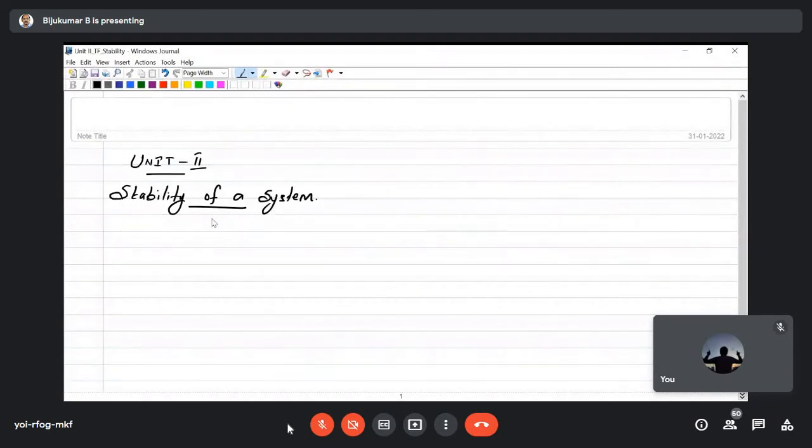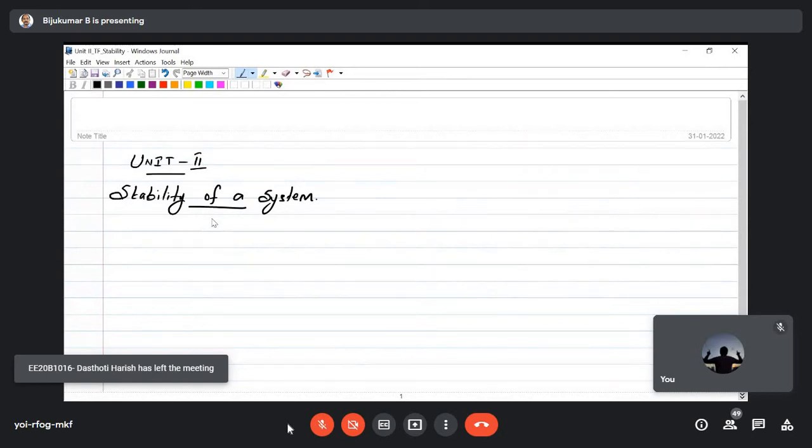So if you give a test signal and if you are checking the system and if you see the output, response can be divided into two parts. One is free response, other one is forced response. Free response is response due to the initial condition, and the forced response is the response due to input. And further, we have seen how to reduce it. Suppose I have a big plant having a lot of blocks, how to reduce that blocks into a single transfer function using some fundamental rules.